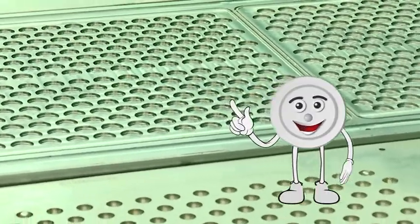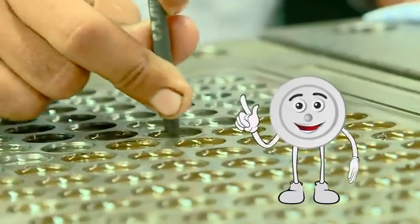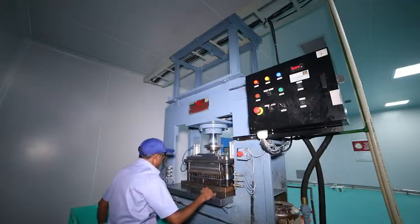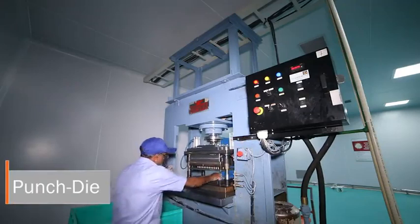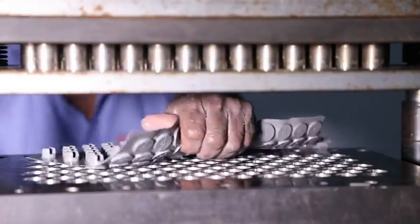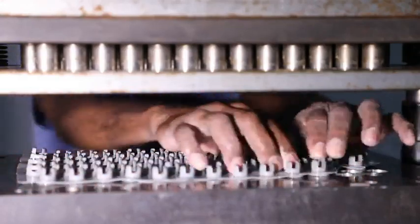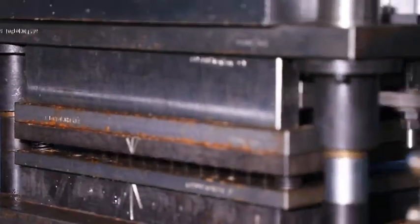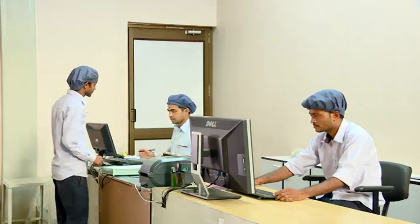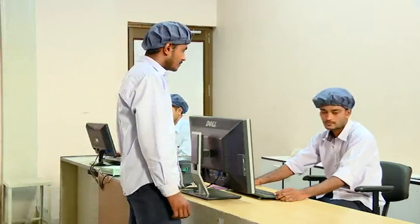After the molds are created, they are polished using a range of tools and equipment to achieve flawless finishes on molds. Towards the end of the manufacturing planning, the punch die assembly is created mainly using the punch and the die. The punch and die are fixed on the machine in such a manner that the two are in perfect alignment. When the punch along with the ram of the press moves downwards, the punch passes through the die. At this stage, when the manufacturing is ready to start, the raw material is requested from the stores department.